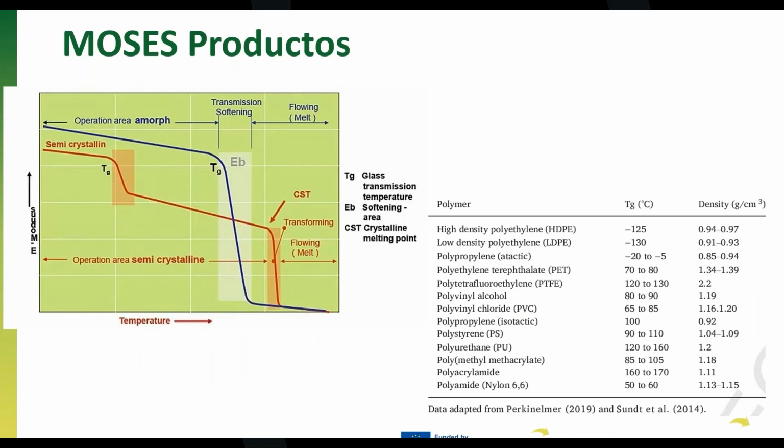And then the Tg is really important for crystallization. We need to decide which properties we want from our material. We need to know this Tg in order to adapt the mold, or depending on the technology, other cooling processes, so that we will be sure that we have this phasing here.